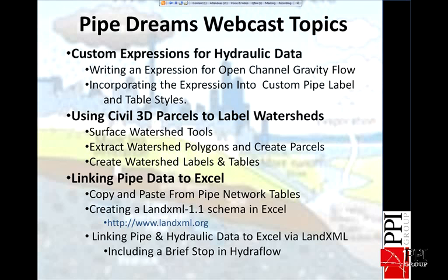So these are the topics that we have today for the Pipe Dreams webcast, as I said. First, I'm going to get into using custom expressions for hydraulic data, and what I have is I've written an expression for open channel gravity flow, Manning's equation, within the expressions, and once it's an expression, you're able to bring that expression into a label style and table style, and be able to show the full capacity flow of that pipe as you're moving along. It's just a good design tool.